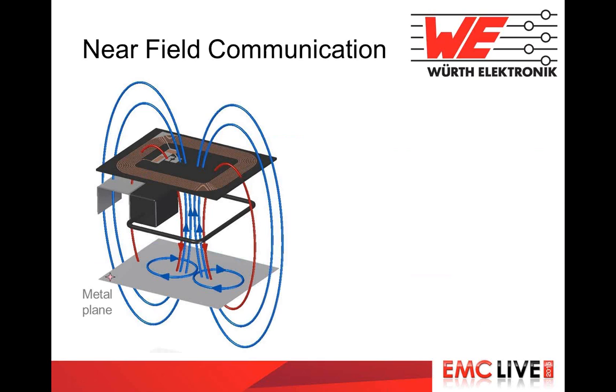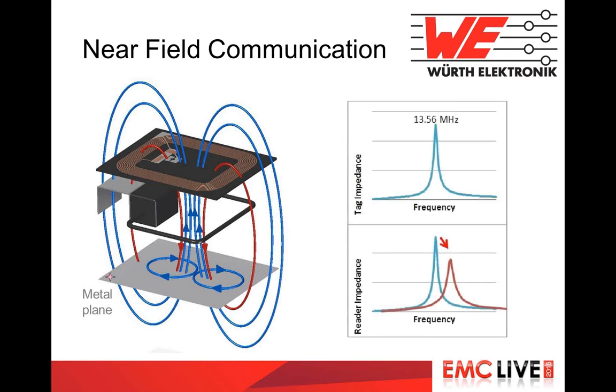Let's see now the near field communication application. It's similar, but it's not. The problem is not exactly the same. In this case, we are not working with power. We are just sending data, so it's not so sensitive to electrical field. Our devices are not so in danger. It is based on resonant frequency also, but at a higher frequency. We have two coils that are the emitter and the receiver, and both are resonant at a common frequency.